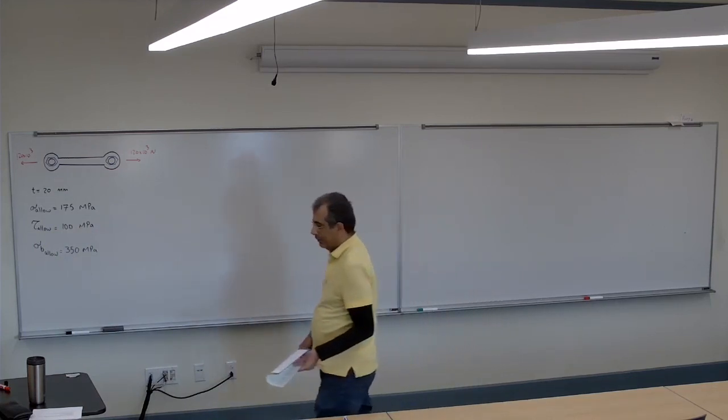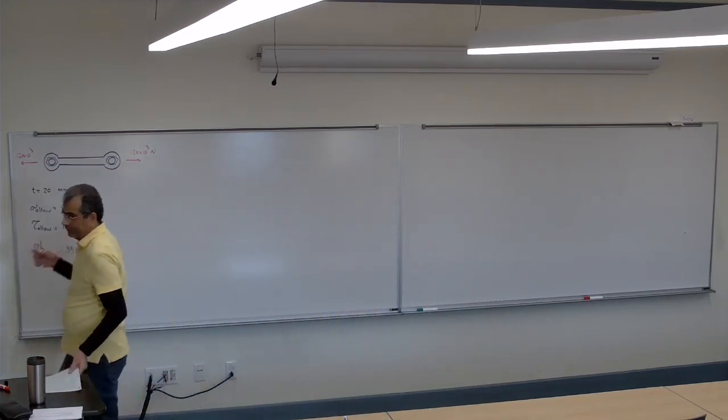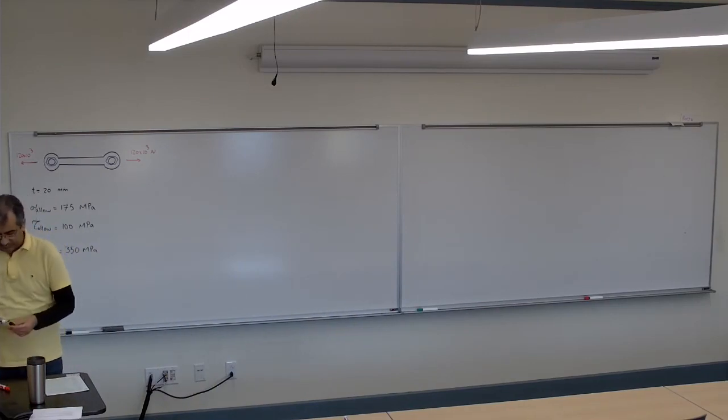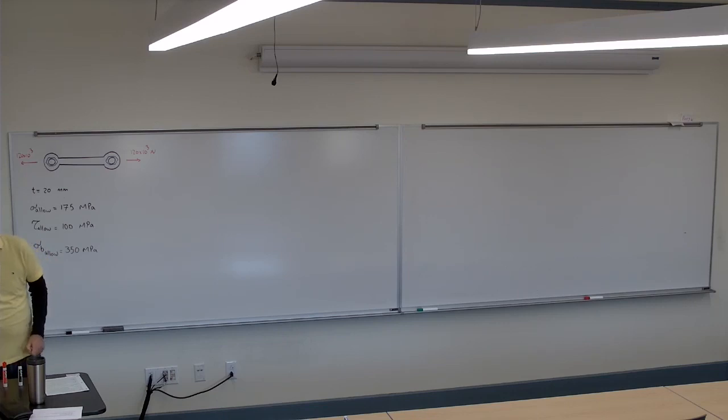Okay. So what would you do if you are given this? Since it's under tension, we know that the failure points are going to be the joints, or where the holes are, I guess. And so we need to make sure that those are able to maintain that force. The holes are usually the weak point.